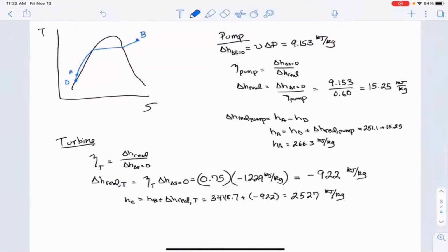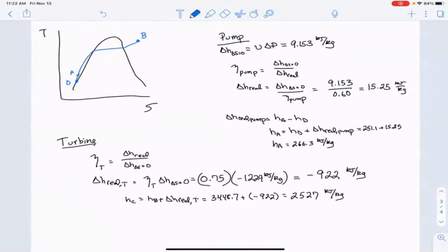And here I'm gonna do this so if people are still writing, they can catch up. So we need to figure out, are we saturated vapor? Are we subsaturated? Or do we have a quality that's less than 1? And the answer to that can come from the values that we looked up in the previous problem. So remember that the enthalpy for saturated liquid was equal to 251.1, and the enthalpy for saturated vapor was equal to 2609.7.